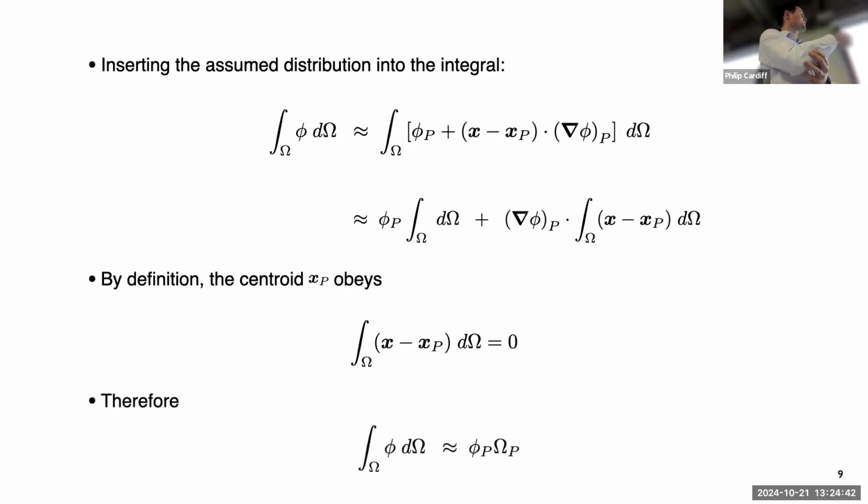So if we only have the first term, we can approximate some field phi over the volume by assuming this linear interpolation form. This thing drops to 0, and then for this term here, you just integrate 1 times the volume. That's just the volume by definition. So that means the term just becomes the value of phi at the cell center, p, times the volume.